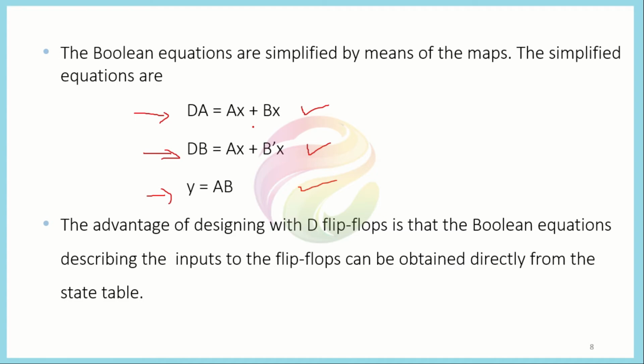Because we were using 4 states here, for a 4-state system, you know that you need to represent it in at least two different variables, A and B. Each would be representing a flip-flop. So A and B are representing the outputs of the flip-flops, and they would form 4 different combinations, and depending upon their inputs we can easily calculate what the output of the system would be.